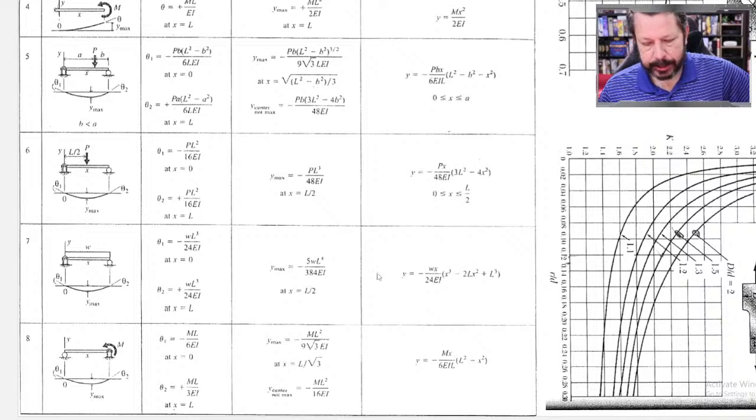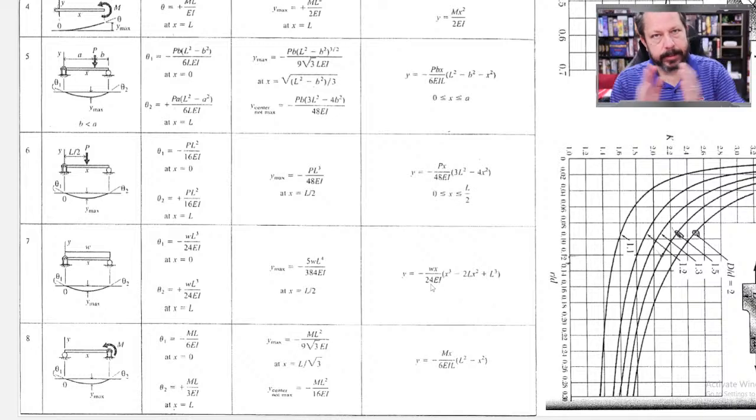We have just this equation of the elastic curve. So we need this entire equation. And since it's evenly distributed and goes across our entire beam, minus the cantilever section that we're ignoring for now for this part of the problem, then X doesn't matter which direction we measure X from. We'll just measure X from the left end side like we had set up. But let's put this equation in.